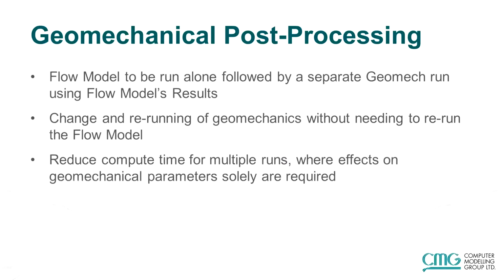The next concept I want to introduce is the concept of geomechanical post-processing. Now, in some cases, you may not run geomechanics because maybe you were not aware of it. You can still run geomechanics without rerunning your flow simulation, as long as you have the restart results. And that's what geomechanical post-processing is about. It allows you to run the flow model alone without considering any geomechanics, and later on adding geomechanics and changing geomechanics in whatever way you want without the need to rerun the flow model.